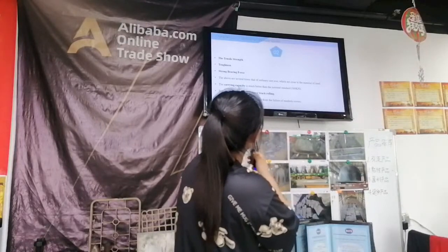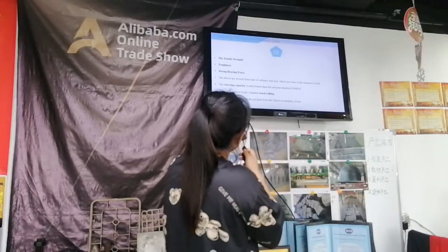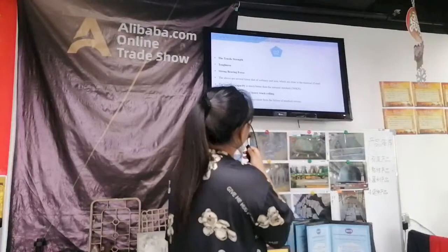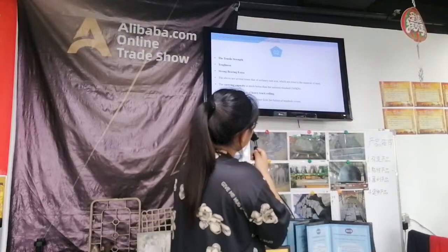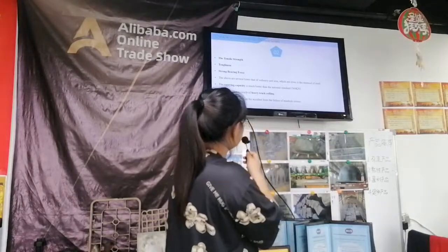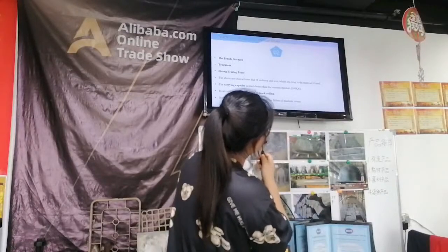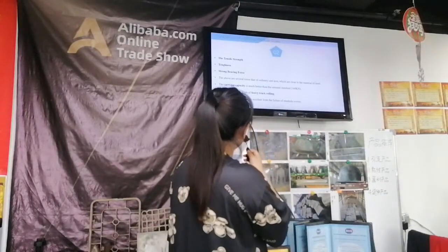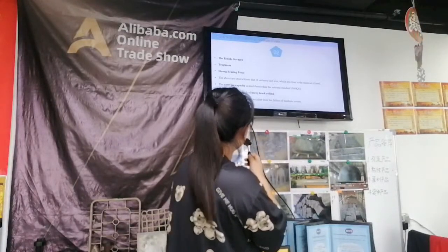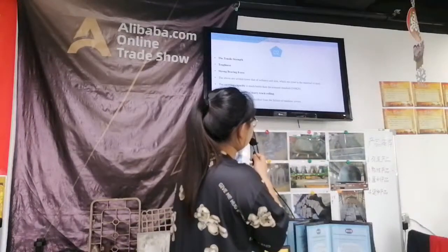Another characteristic of a ductile iron manhole cover is its tensile strength, toughness, and strong bearing force. These are several times that of ordinary cast iron and are close to the material of steel. The carrying capacity is much better than the national standard. The standard is 360 kN. It can withstand all kinds of heavy truck rolling, and it can effectively prevent accidents from the failure of manhole covers.